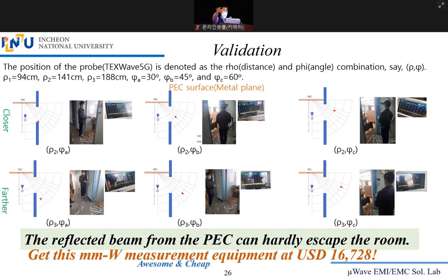For the repeaters developed by Samsung Electronics or KMW or ACE Antenna, they give higher input power. For us, we use an input power of 20 dBm, 10 dB lower than that of the commercial repeaters. That's why we cannot take it to such as 50 meters or 70 meters.